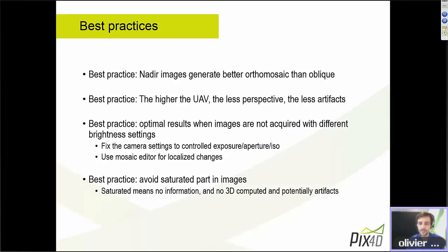Another important lesson is that the 3D model is extremely important to generate the orthomosaic, as this will correct most of the perspective without creating artifacts. So make your datasets such that the 3D content can be nicely generated, and usually this is by having sufficient overlap. This definitely helps to automatically have a nice orthomosaic.